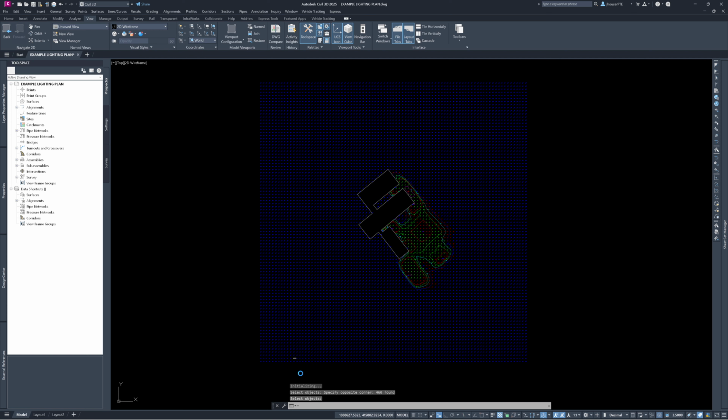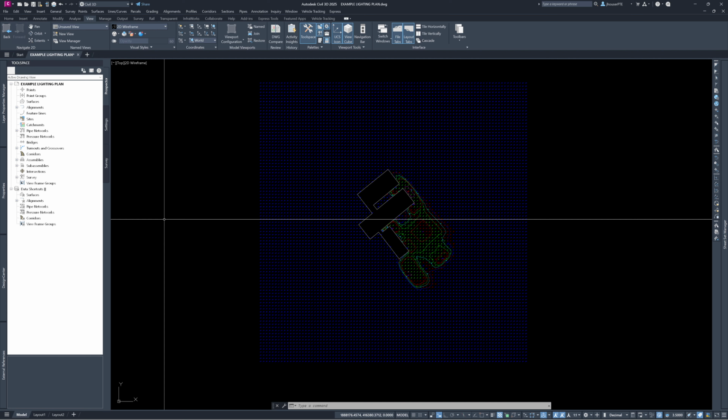Really all there is left here is a lot of manipulating the text, the colors, the layers in order to make it look or go within our CAD standards. Oh, there's one thing that's real important. I have created a script that helps to do that process. So we audited, or we recovered. I'm going to do a quick purge on this. I want to get rid of everything that it brought in that's extra.